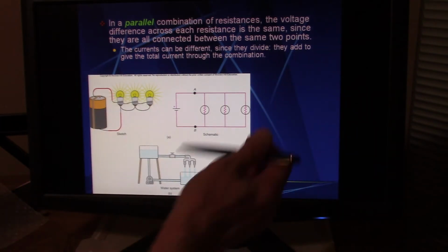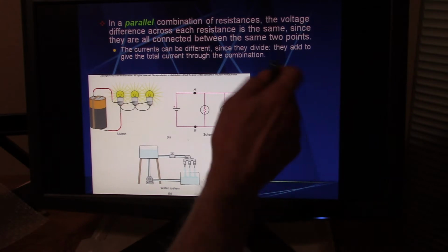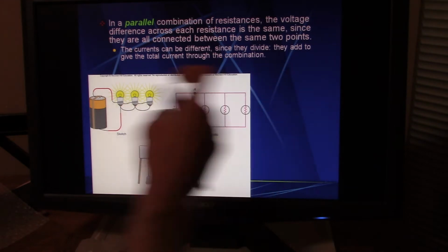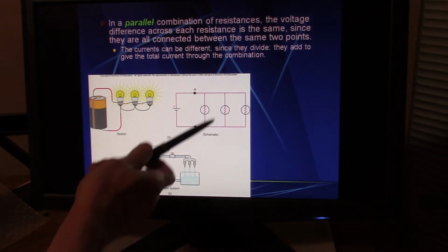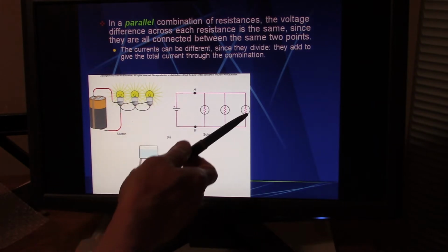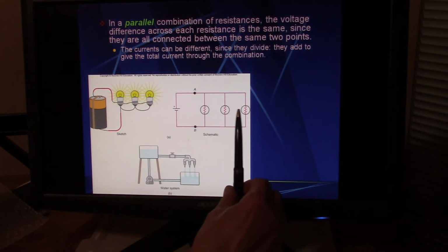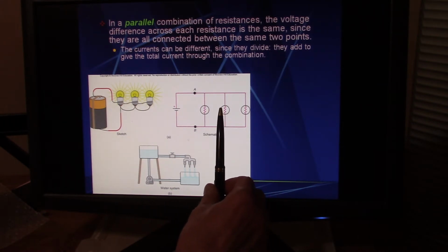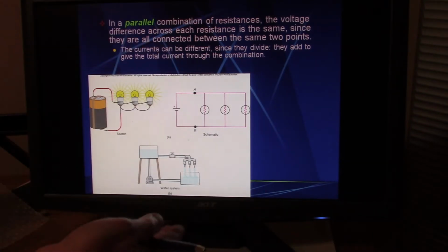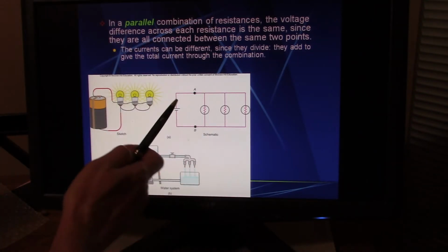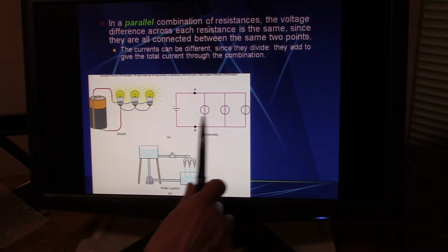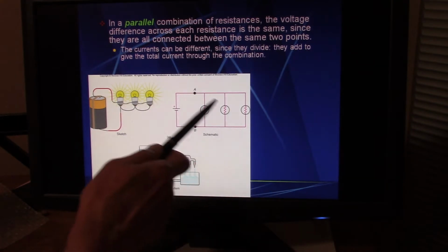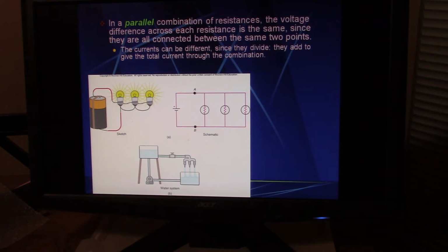Your radio in your car would have a resistance and work on 12 volts. Your headlights and brake lights also work on 12 volts. So everything works on 12 volts, and they each get their individual current depending on their resistance. Your light bulbs are going to have a different resistance than your car radio, and a different resistance than your electric window that goes up and down. But they're all going to work on 12 volts. So this is the way your car is wired. All these different devices get the same voltage. They can just make them for 12 volts, right? Okay?